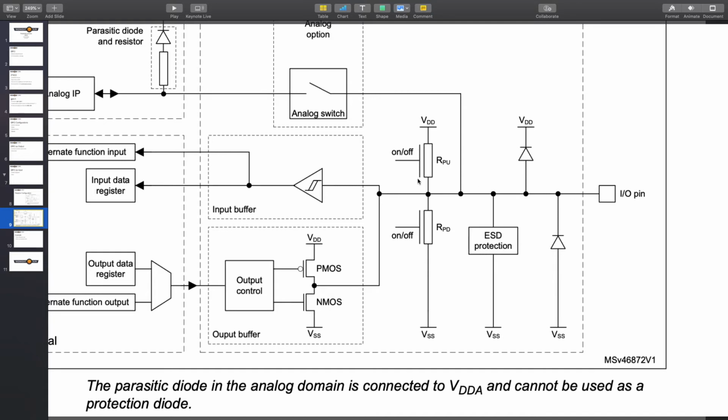The resistor configuration is there for the pin's default behavior. If this is not connected to anything, or if it's connected to another component that has a high impedance, that's as if you have connected nothing to this line. So what would be the voltage of this line if it's not connected to anything? Well, you wouldn't know, because there's nothing inside this circuit that would pull it high or low. Let's assume that these diodes don't do anything. This is just electrostatic discharge protection. If you have some static discharge, like you just touch the pins, that protects that part.